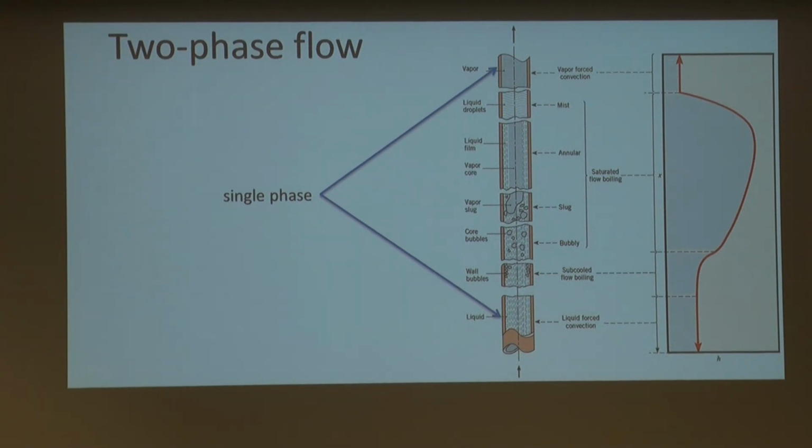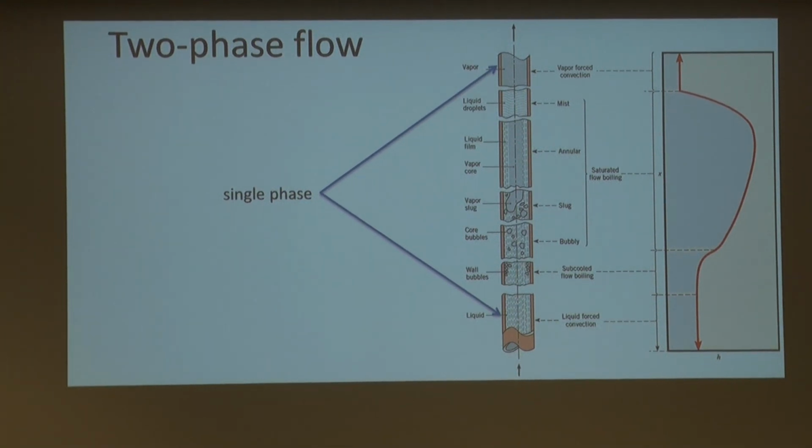Now, this curve on the right is the heat transfer coefficient for different parts. Before we have any bubble, when it's all liquid, you know exactly what to do, and Nusselt is more or less 4. That is something that Ying taught when she taught internal flows.